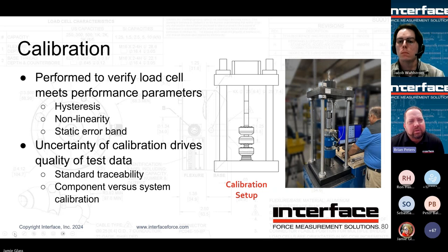And then from there, we go to hydraulic reference standard cal, which is what's depicted here, where we're using a couple load cells to track. So in that schematic, we have a load frame. That top unit would be the DUT, or the unit being calibrated. The unit below that would typically be our calibration standard, where we have very high confidence. That goes back to NIST for calibration. Some of our standards in our lab are older than 40 years, believe it or not. So we have binders and binders of history and extreme confidence in those standards. And then depicted under that would be the hydraulic control sensor for the hydraulic frame. That one would be controlling the actuator to monitor the applied force. So this is a good depiction here.